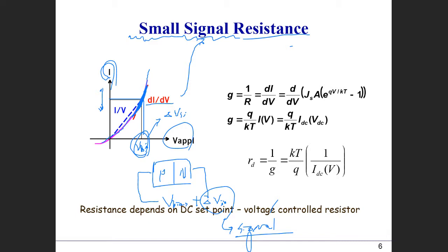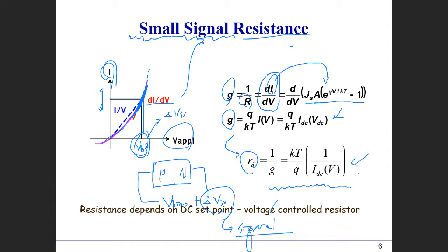So simply, in terms of conductance, it is one over the resistance, which will have this kind of relationship. Okay. And then the current of the ideal diode follows this equation. So from this relationship we can obtain the conductance value for the PN junction diode, and from there you can obtain the resistance value. So the small signal resistance we can obtain from this equation.